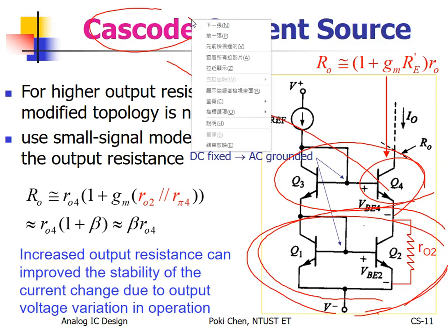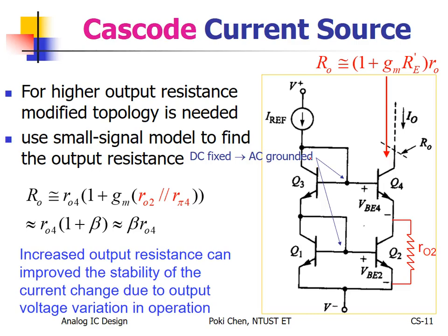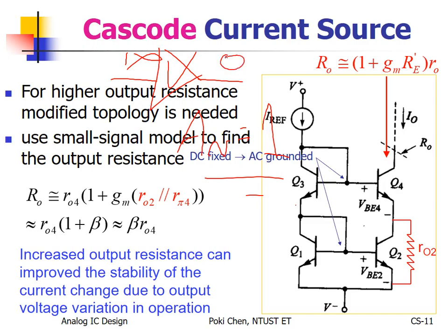I think you are much more familiar with the voltage domain. So allow me to ask you, or allow you to ask yourself, what is the function for a voltage buffer? It means no voltage gain. In the voltage domain, what do you want from such a no-gain buffer? You need very high input impedance and very low output resistance, right? And why? Don't ask me, okay? That is the very fundamental idea. That is too low-level for me. I'm your analog IC teacher, not a fundamental microelectronics teacher or fundamental circuit teacher.